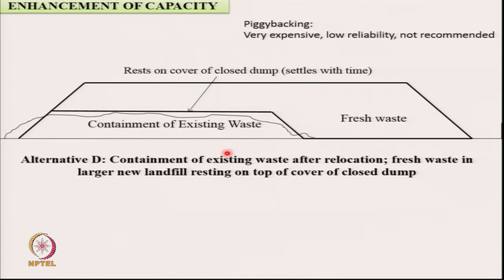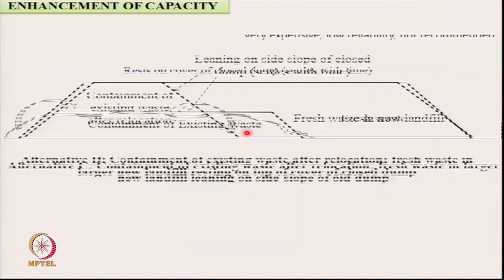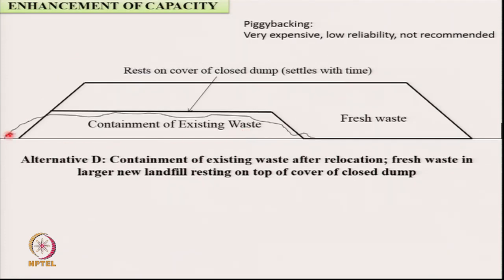Yet another alternative is, why should I waste the money to pick up this and put it on top, pick up this and put it on top and then do this? Let me do the following. This is called piggybacking. This is my old landfill. I will close it and I'll raise my new landfill on top of the old landfill. This is called piggybacking in America. Here it says piggybacking, very expensive, low reliability, not recommended, because this is going to settle.